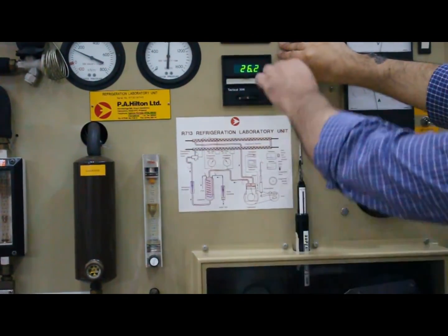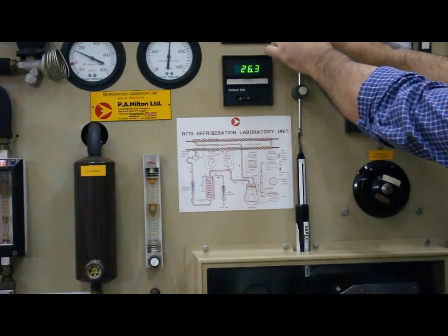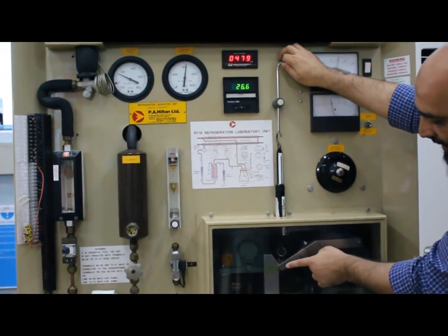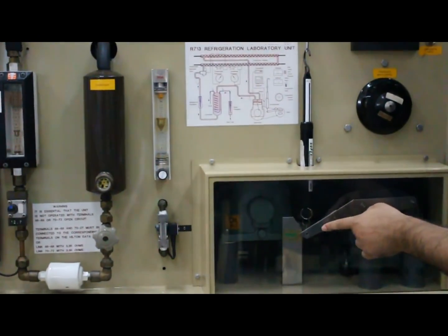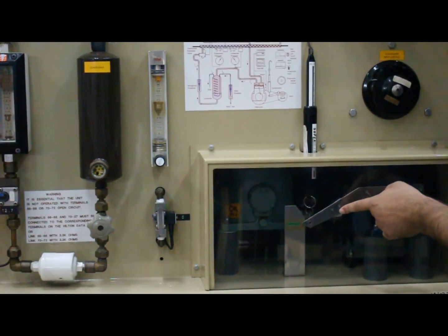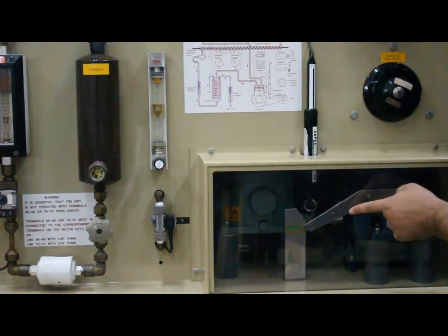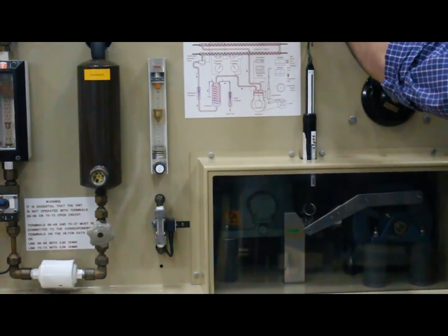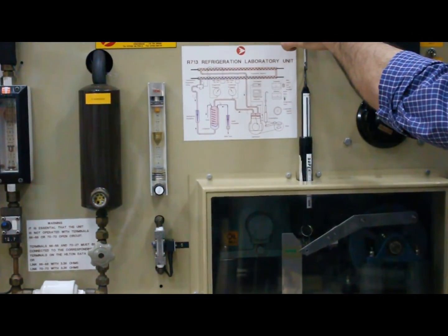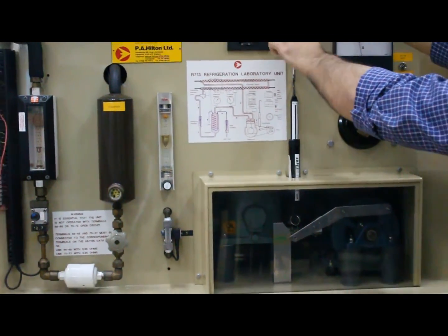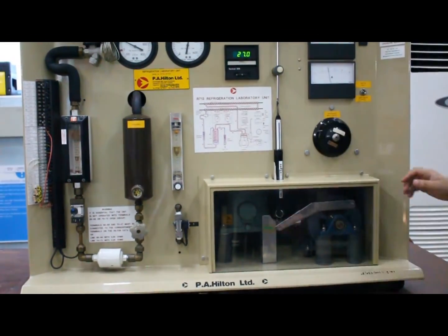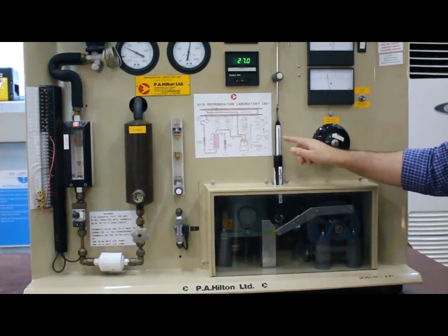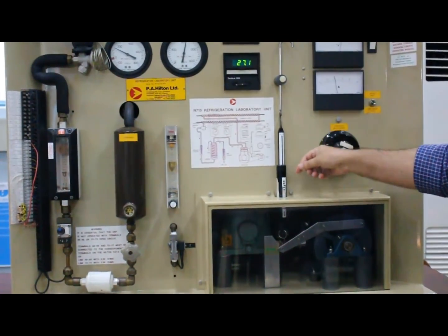move this spindle upwards, and in that case you have to focus on an arrow that is being shown over here. This arrow should be in line with the mark of the lever that is attached over here. Once it is in line with the mark, you can tighten up this spindle, and now you can read the amount of force being applied using the scale given on this spring balance.